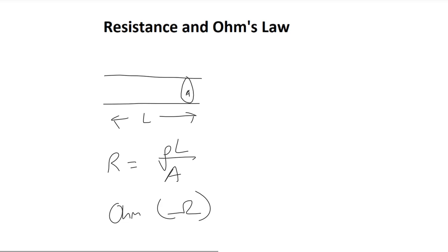Based on this unit, if you rearrange this equation for the resistivity, you will find that the resistivity has units of ohm meter, ohm multiplied by meter. I encourage you to check this in your own time. One final thing to note about resistance is, although it is not clear from this equation, most conductors have a greater resistance at a higher temperature. As the temperature of a solid increases, those particles within the material vibrate more frequently, at a higher rate. Such vibrations create a greater resistance to current, a greater resistance to the flow of charge.